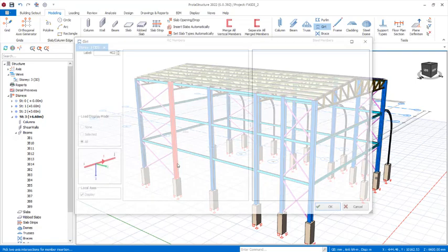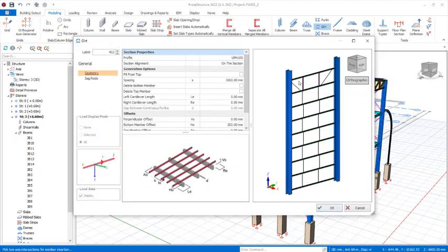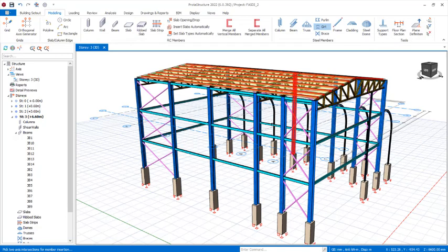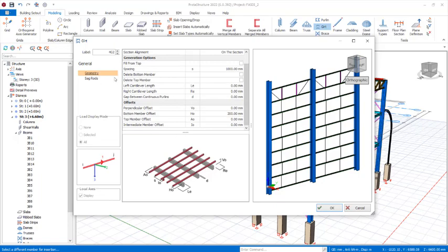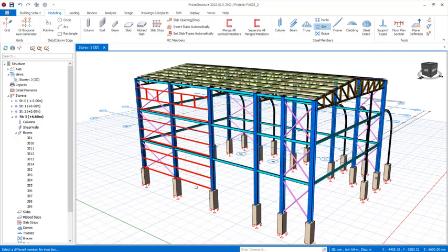and you wait for the program to respond. So here is the gate just like this. Okay, so I will cancel this and I will do that again. I want to be extending it from this point to this point because this provision is an entrance. So I'll pick this and this, sorry, this one and this one. So for the gate's property, you can see it here, the profile. You can make changes, this spacing, you can also make changes over here. All right, so for me, I'm okay with this. For the sake of this lesson, click on the OK options.